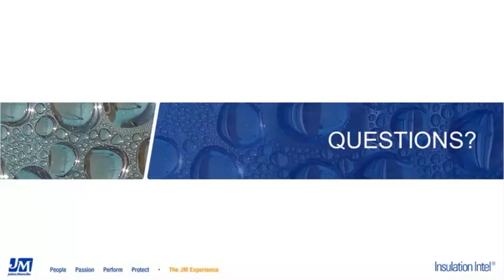Sure. Basically, the XPS PIB, or what people often refer to as styrofoam, is not a product that would be used in a commercial building chilled water application due to its flammability issues. But XPS PIB styrofoam is really the most popular insulation in refrigeration applications, and I guess that might be a good topic for a future webinar.